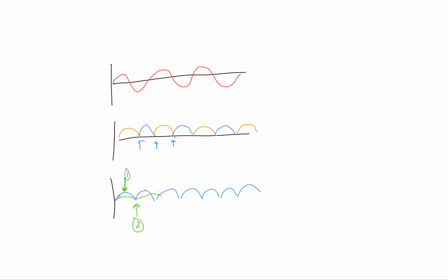And so what you actually get is a little, I'm not drawing this very well, but you kind of get the idea, right? It's a much more even flow of electricity with little ups and downs and not the big ups and big downs that normal DC is. So capacitors are put in there to hold on to some energy and let it out a little bit when it needs to, store it back in when it needs to. Okay, so that's how we convert AC power to DC power. Okay, all right.